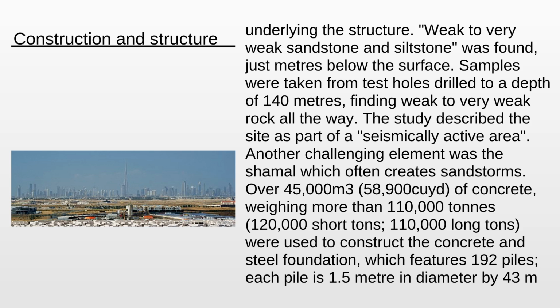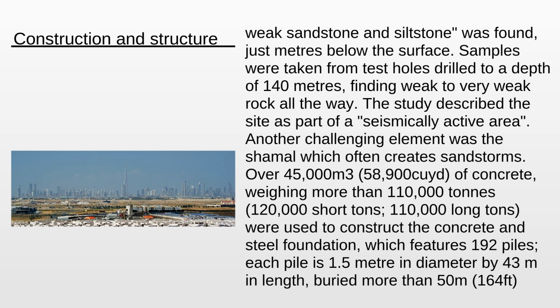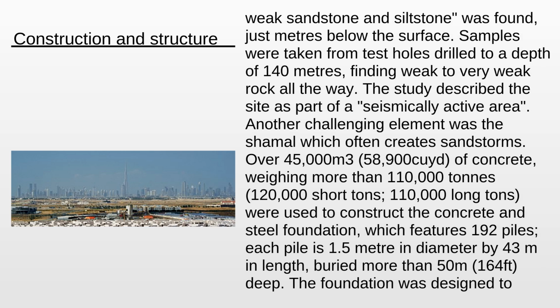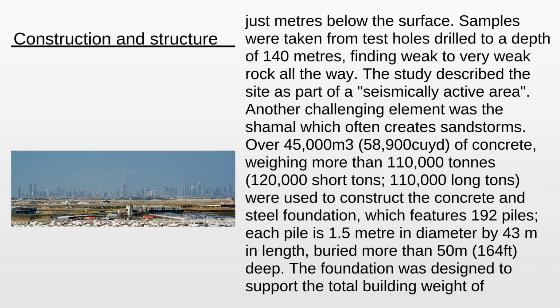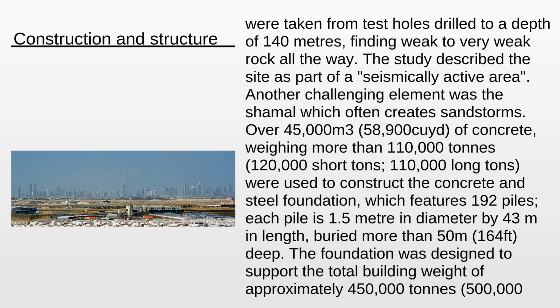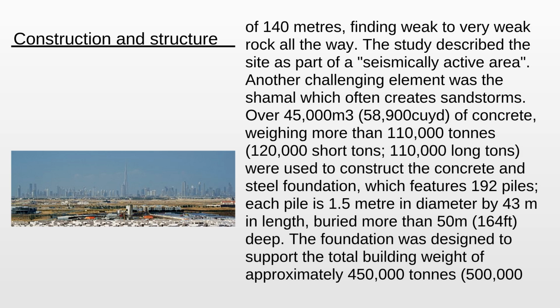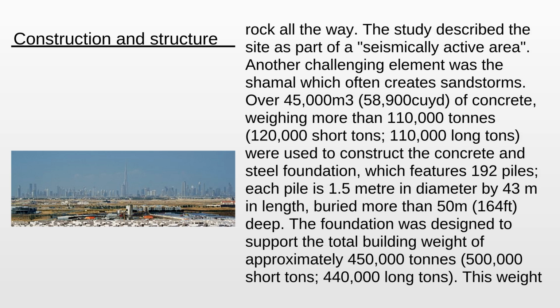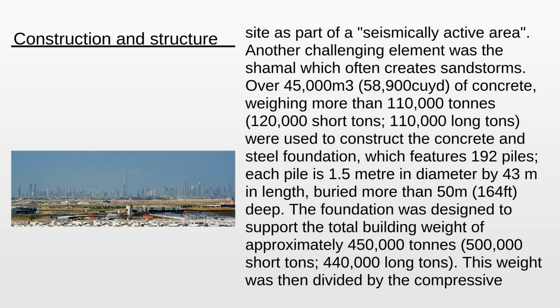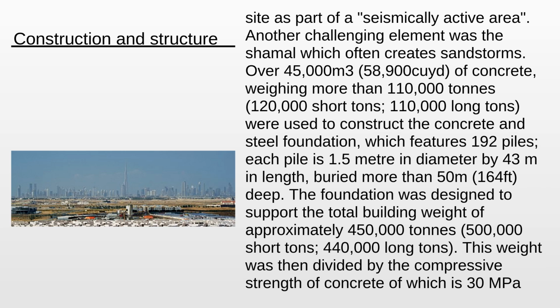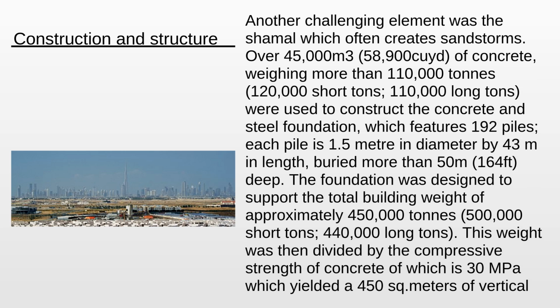In 2003, 33 test holes were drilled to study the strength of the bedrock underlying the structure. Weak to very weak sandstone and siltstone was found, just meters below the surface. Samples were taken from test holes drilled to a depth of 140 meters, finding weak to very weak rock all the way. The study described the site as part of a seismically active area.